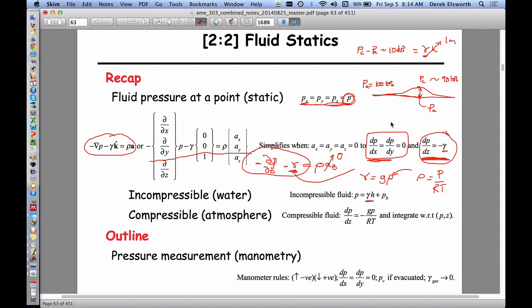And so if you think that the storm surge is purely due to that low pressure, it certainly contributes by adding 1 meter, but to get 6 meters of storm surge rather than 1 meter, you have to take the coast of New York or wherever it is, and have this being bulldozed onshore, this being bulldozed offshore.